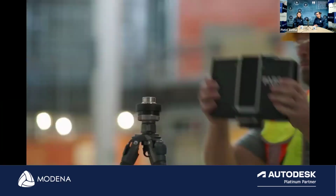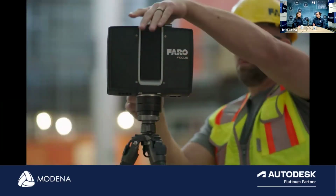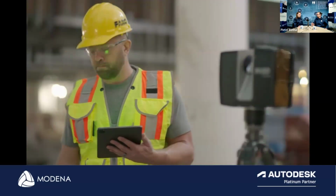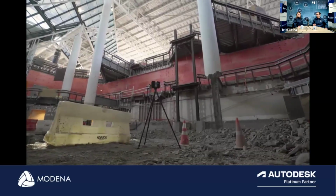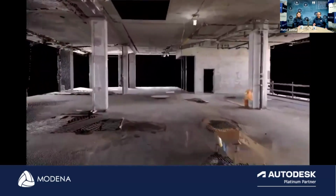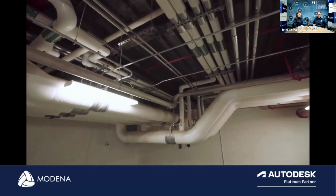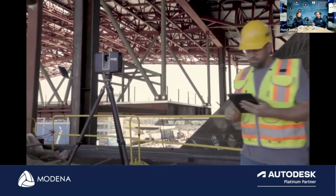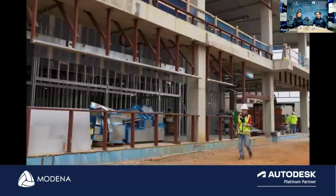All right, so for those people who don't know how 3D laser scanning works, I'll just give a very quick brief overview. 3D laser scanning uses a laser that is being emitted from the scanner, and when it reaches an object, the laser is returned to the scanner, and the distance is calculated to provide you with an X, Y, Z coordinate for every single point that is being measured in that space. So there are different resolution settings we use as well. We can scan from 1.1 million points, all the way to 699.1 million points per scan. That's quite a lot of information.